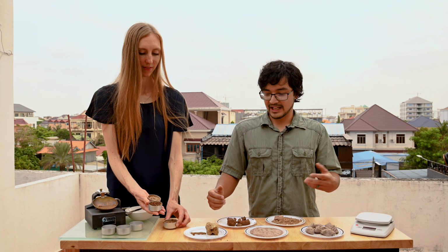The second sample is in the moist or damp condition. The moist condition is usually when the soil begins to darken by the presence of some moisture. And the last one is when the sample is in a wet condition. These soils are usually found near the surface of the groundwater table, and when you retrieve the sample, there's visible moisture at the surface of the sample.